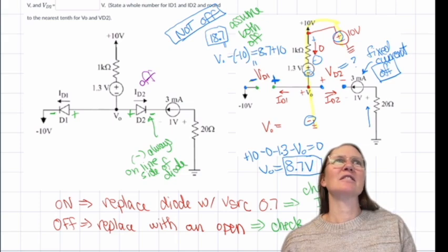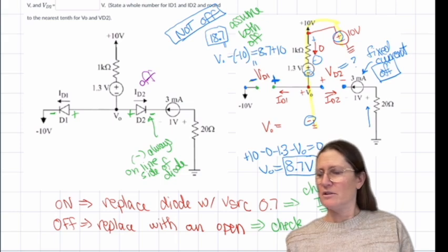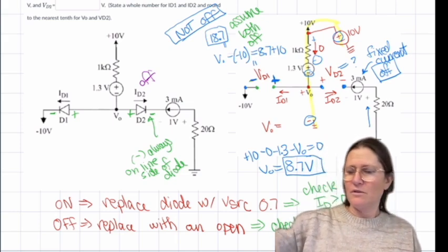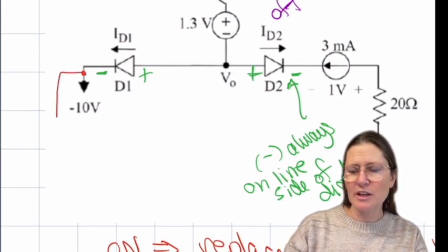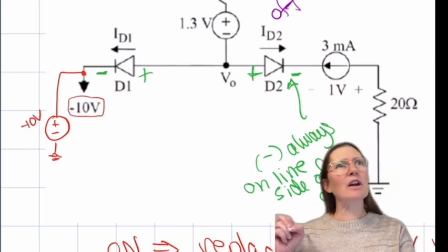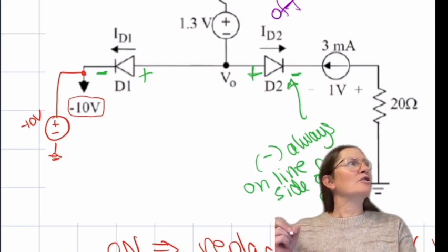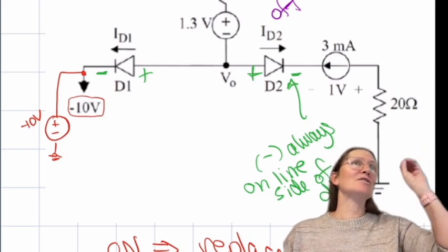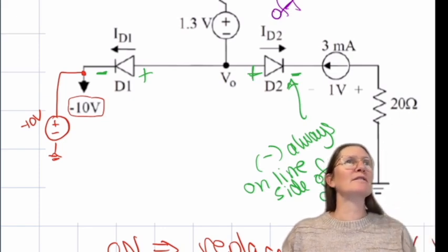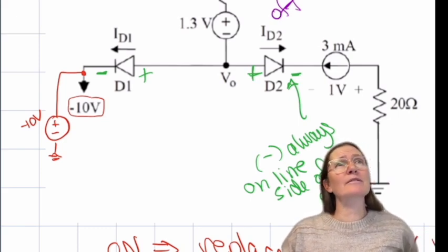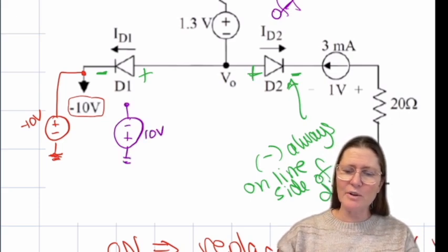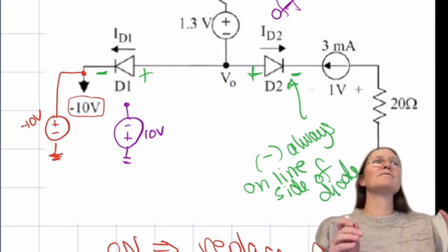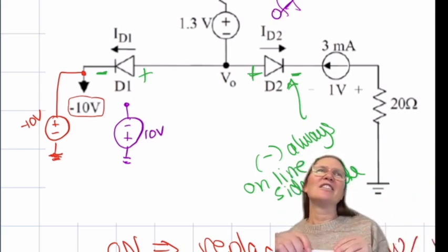Yes? How would you draw that negative 10 volts as a battery next to ground, like the down arrow? Okay, it says negative 10 volts. You could draw it two ways. You can just connect a plus-minus source to ground, and then label it whatever value it says. So this would be plus to minus to ground, with a value of minus 10. That way you only have to remember one thing: wherever it has an arrow up or down or a dot, just draw a connection from plus to minus of that point to ground, and then label it whatever the value says. Or you could draw it as a plus 10 with a minus to plus connected there. Whatever way you visually see correctly, they mean the same thing.